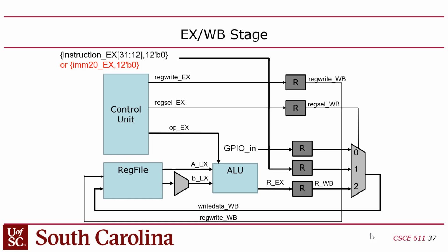So the ALU has a 4-bit signal that tells it what function to perform. And in many cases, that's the only thing that really differentiates one instruction from another. Like if you have an add instruction or a subtract instruction, they're the same, except the ALU code is different, right? Does that make sense?